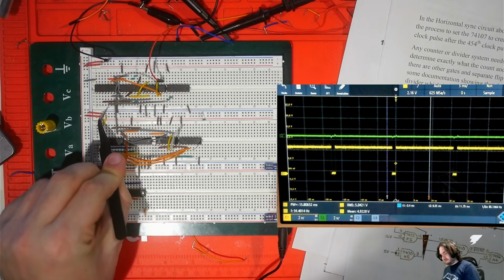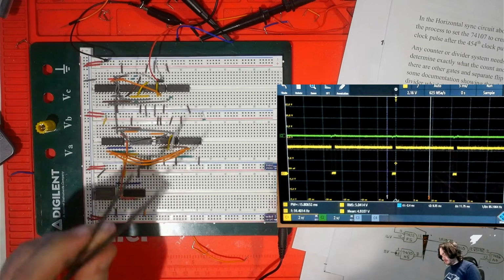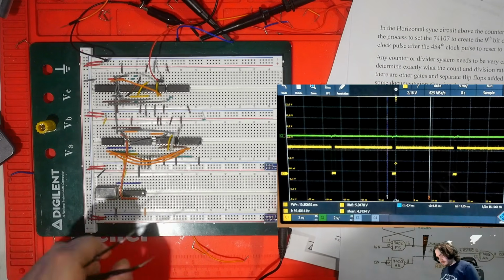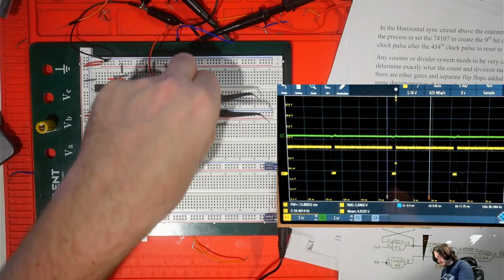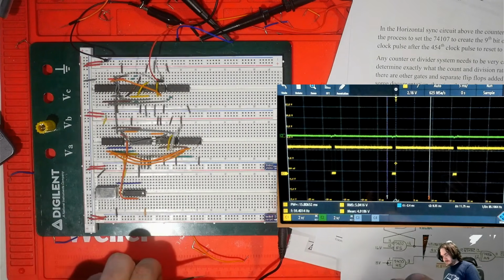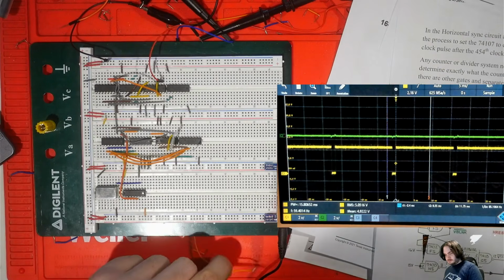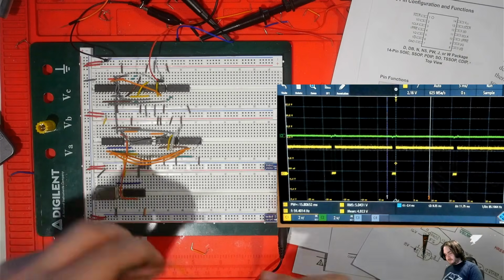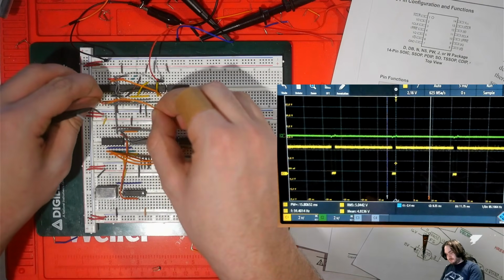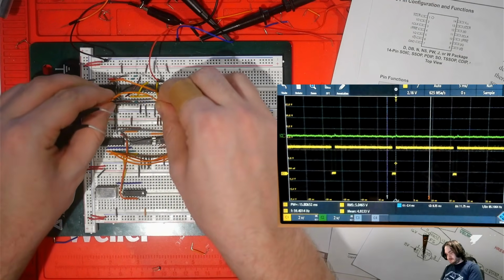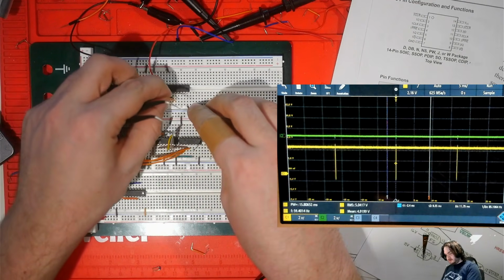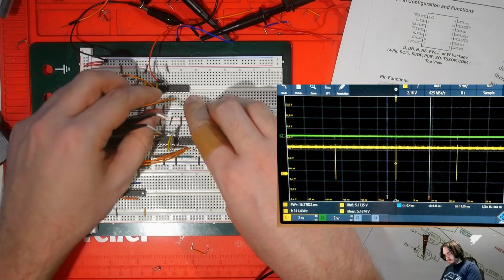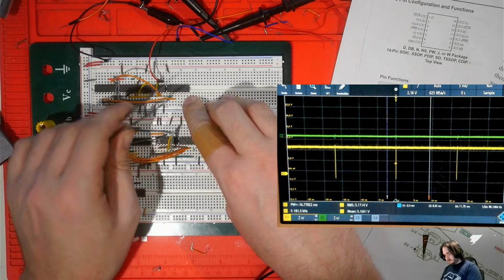So this is 8V, and we're inverting that as it says to do there. Next, we're going to NAND that with 4V, which is third from that first corner, actually pin number 3 by the official numbering. That's not it.